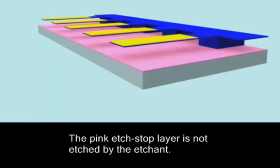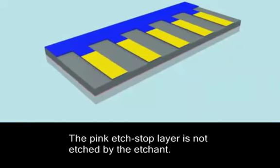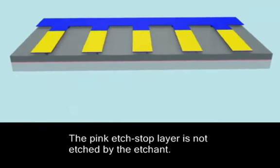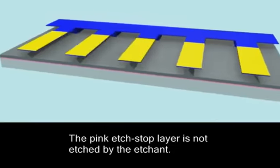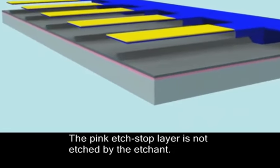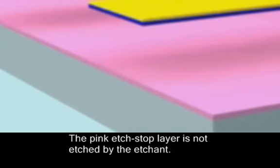The pink material is an etch stop material, which could also be silicon nitride, for example, and that keeps the etchant from continuing through the entire wafer. Now we can also do boron doping of the crystalline silicon, which greatly reduces the etching of potassium hydroxide. So that's another way to do an etch stop.